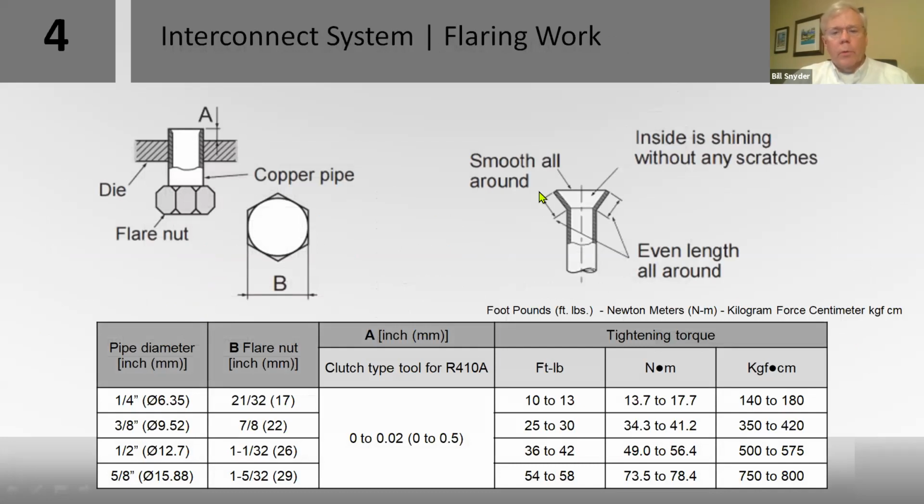This again is talking about putting a proper flare, using a good quality flare nut, and torquing the unit to the proper foot-pounds or Newton meters or kilogram force centimeter is what this is. It doesn't really make any difference. The charts will show all three. So if you buy yourself a good torque wrench and you get it home and it happens to show Newton meters, not a problem. This is your conversion on here.